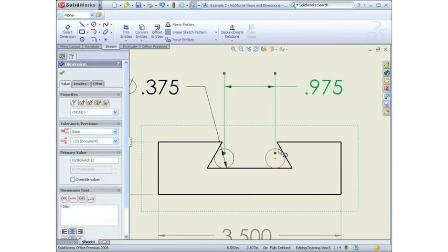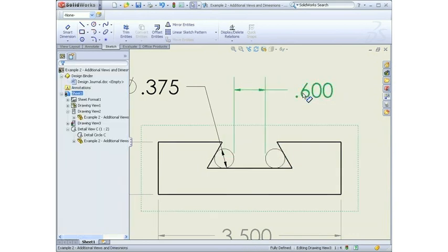Now there's one more modification we need to make to this dimension, because obviously we've set these dowels in the dovetail, but there's no accurate way of measuring the center to center location of the dowels without simply measuring inside of the dowels and then subtracting from that the diameter, which is possible, but it's easier if I simply select the end of that dimension and drag it to inside the dowels. So now we've got a measurement that can be measured using a vernier.